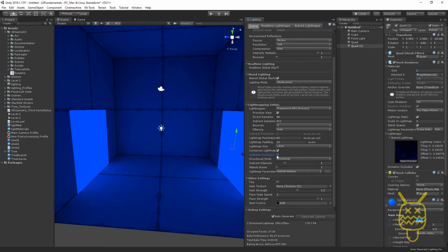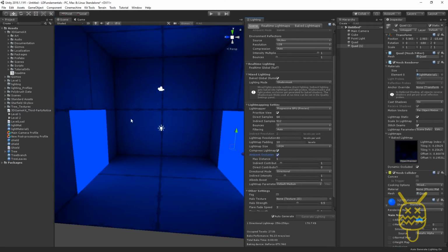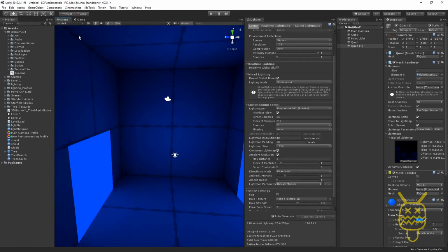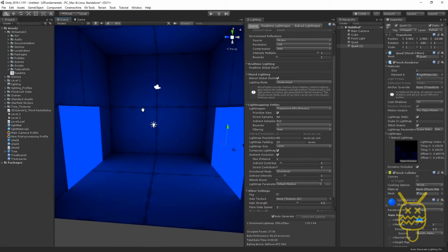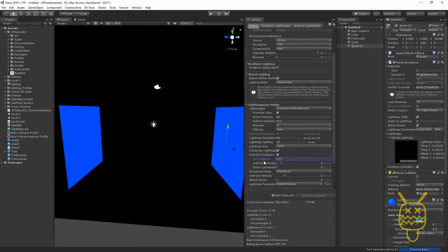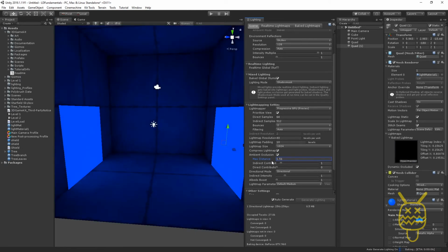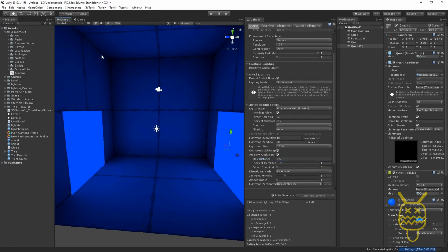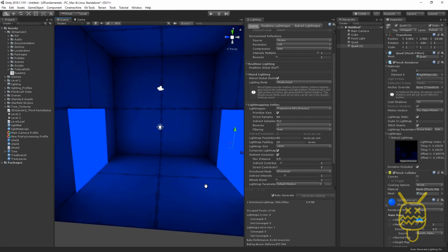The ambient occlusion, if you click on this, is going to create a pseudo shade wherever two surfaces touch. It's going to create a darker shade around those. So for instance, the max distance, if I was to actually increase it, notice that just a very simple increase or decrease is going to show, we'll do 2 on here, how much darker it is. But if we drop this to say 0.5, then we're getting just the edges themselves, which is actually creating the shadow for it.